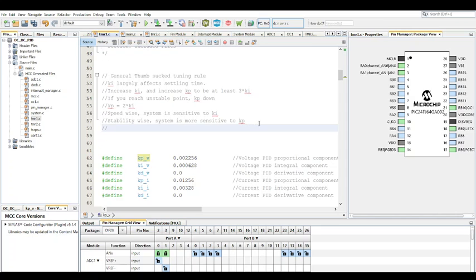on other converters that are not boost, start your KP at this: 0.0003. I know it's kind of overkill. And your KI at least 3 times less than that.